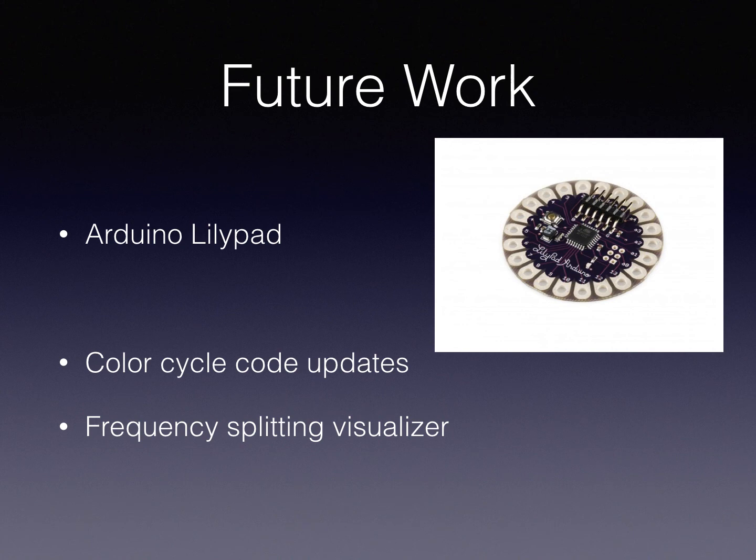So finally, some future work that I want to put into this project would be to get a new Arduino, possibly a smaller one. Arduino makes what's called a LilyPad, which is a microcontroller built specifically for wearables, and you can sew the LilyPad directly onto fabrics, and then also use conductive thread to run your circuits, and so it would be a lot more compact on the bill and take up a lot less space. So that would be the first thing.